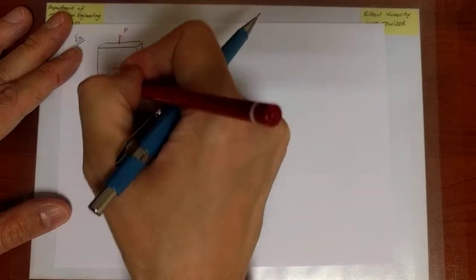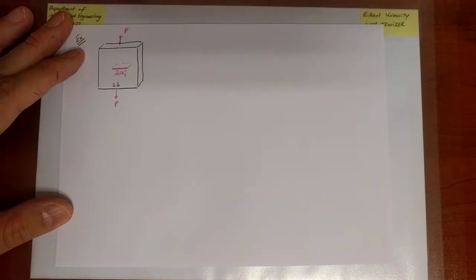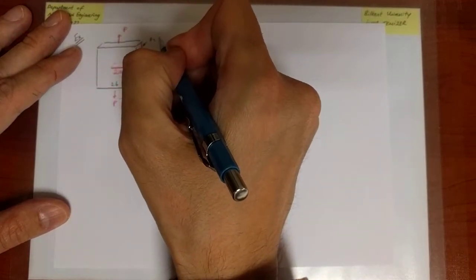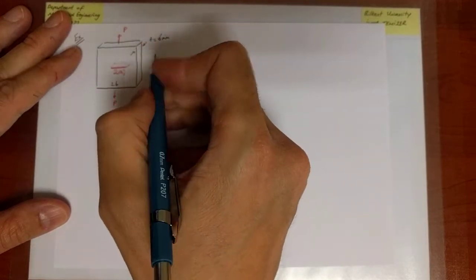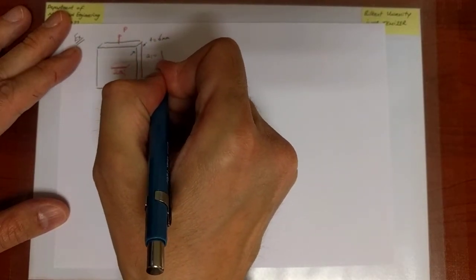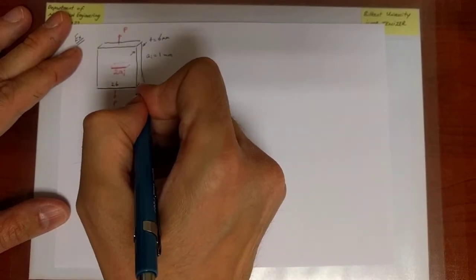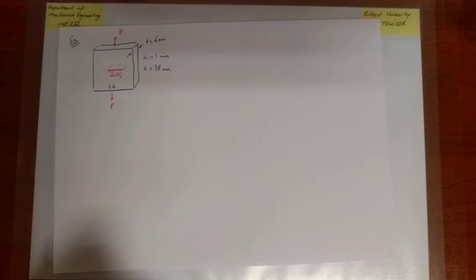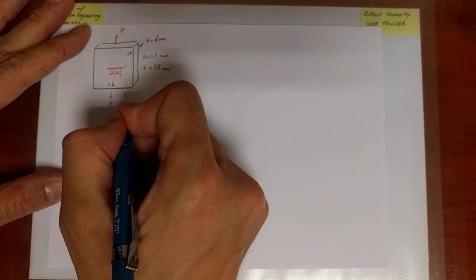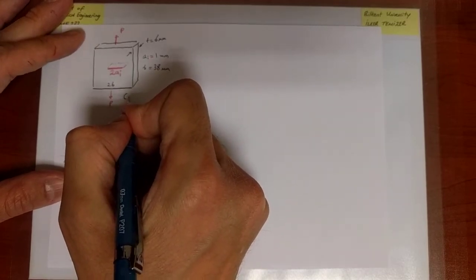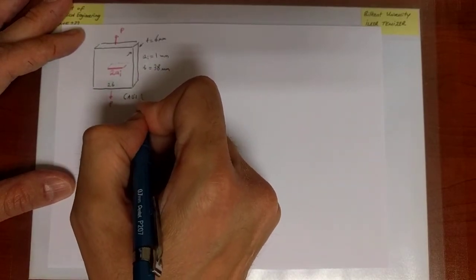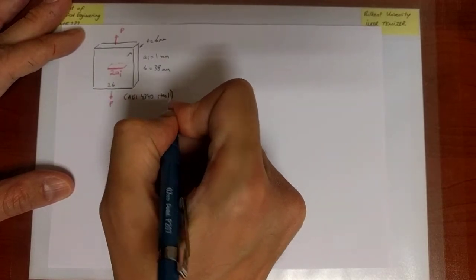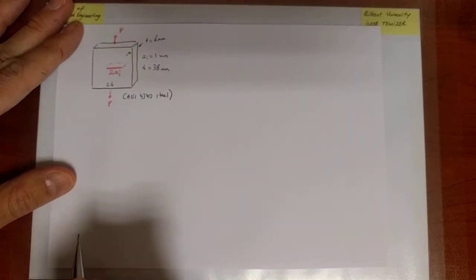It's a tensile loading, which is mode 1, and there is a thickness which is 6 millimeters. The initial crack size is provided as 1 millimeter, and the width of this plate is 38 millimeters. Okay. And the material is given, so that's all that's eventually going to be given. So we would, of course, be expected to find relevant material tables from the book and make use of them to help us solve the problem. But I'm going to provide you with those parameters.